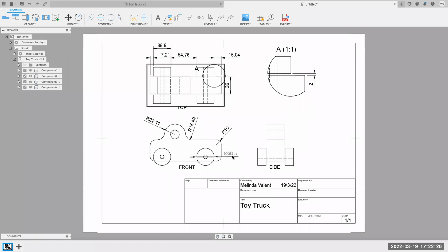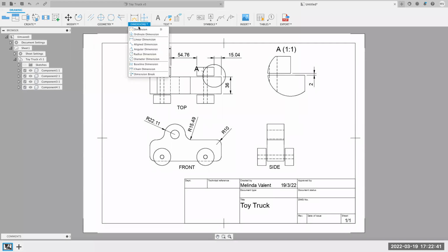So I can also right click, delete it. Yes, delete. All right, so checking, they probably need this one here. Try and avoid dimensioning on top of your object. So here, it really wants to put it on top of the object. I'm going to pull it out to the side so the numbers are not on top of my shape, because again, it's going to clutter it up. There's a lot of information going on, even for such a simple object like this.